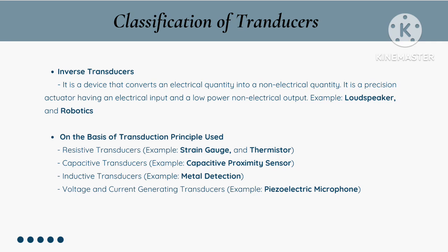As the crystal deforms, it generates a small electrical voltage that corresponds to the sound wave. This electrical signal can then be amplified and used to create the audio output that you hear in speakers or music, or when you make an audio recording on your phone. So, the louder the sound, the more the crystal deforms, and the greater the voltage generated.